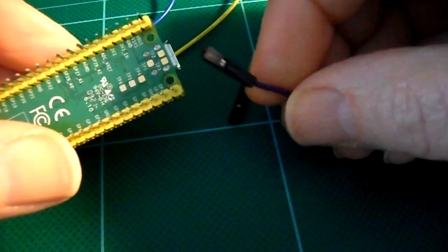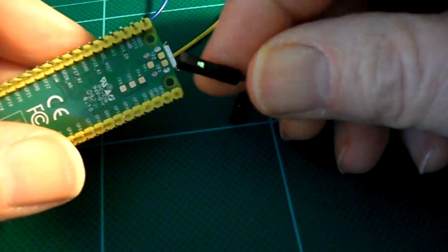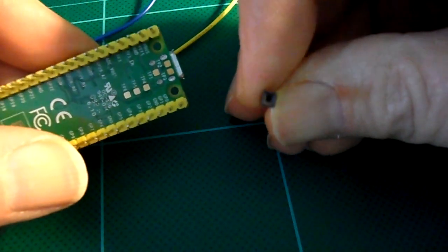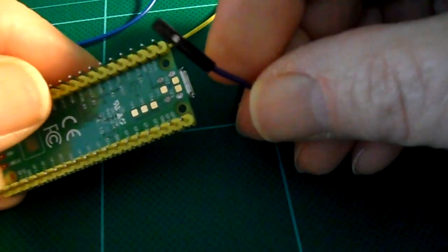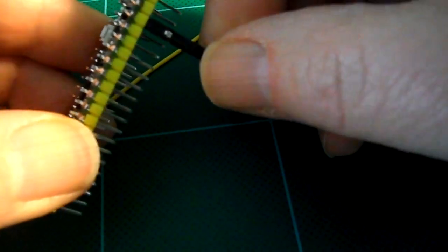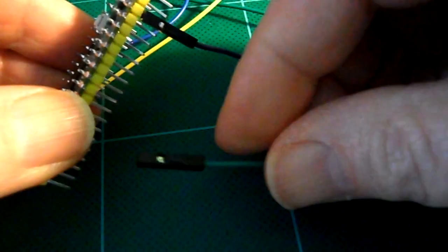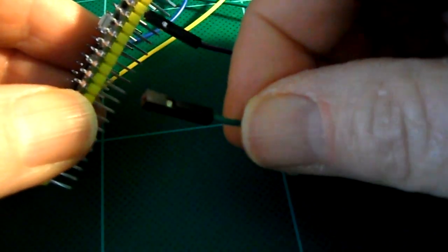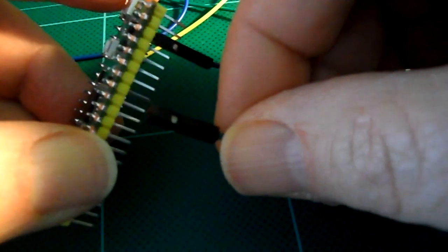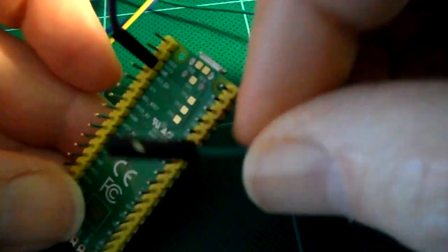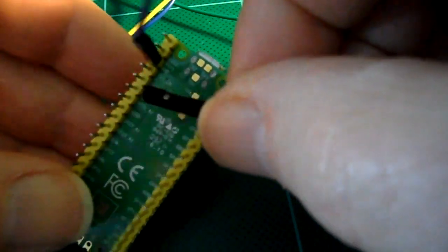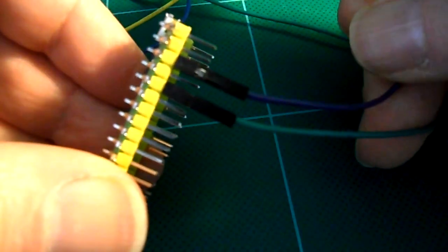So keeping in mind that the purple wire is ground, it comes with a female type connector on the end, so we can just hook it directly up to our Pico pins. So the purple needs to go to the ground pin. And remember, ground is on pin 38. Next, the green wire is the VCC, and we want to run it to 3.3 volts. So once again, looking at the bottom of our Pico, we can see 3.3 volts is on pin 36. So we can just hook that directly onto pin 36.